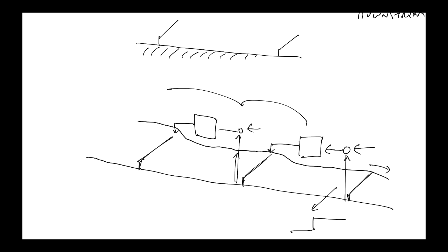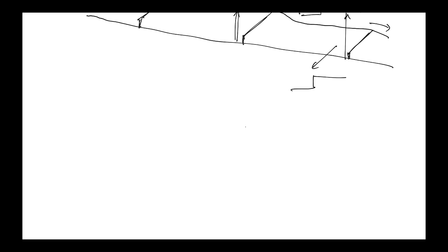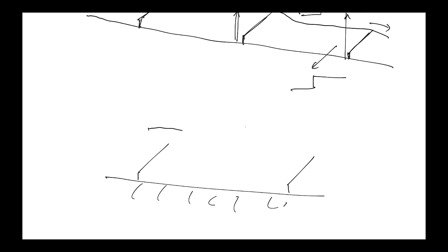Any questions? No? All right, so to do control system design, we need some sort of model. We're just going to look at one pool. A pool is a stretch of channel between regulating structures. What we're trying to do here is control the water level at the downstream end. That's where we will be supplying flow to farmers, and that's what farmers want.